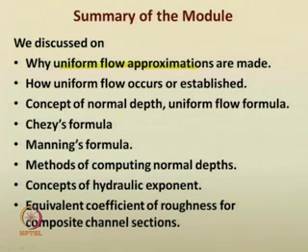We have discussed the concepts of normal depth. We have also discussed the uniform flow formula. We have suggested Chezy's formula, Manning's formula. We have suggested various methods to compute normal depth. I hope you recall them: trial and error method, numerical method, design charts and all. We have introduced you to the concepts of hydraulic exponent. We have also suggested the equivalent coefficient of roughness for composite channel sections, how to evaluate the equivalent coefficient of roughness for composite channel sections.